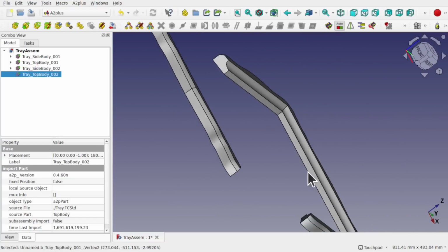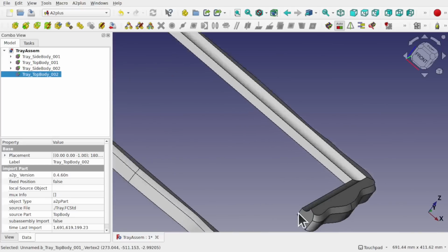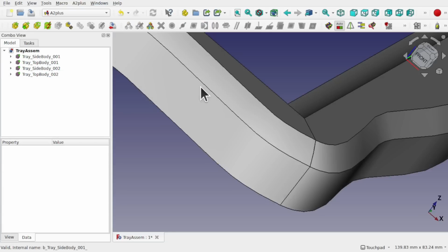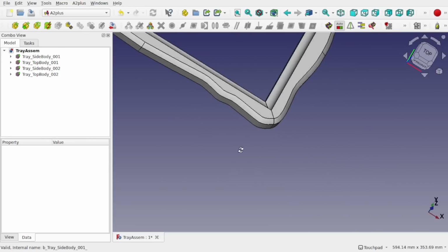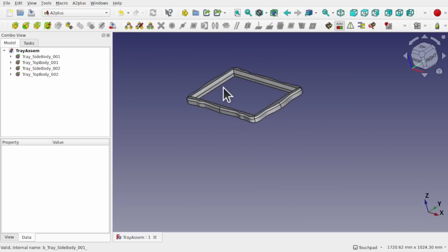Okay, so let's put mouse pointer over here so I can rotate this around, and make sure that we now hold down Control and select this point. Select that line, so click it again, still holding down Control, and select that point. So you can see both of them selected on the left hand side. Coincident on that, accept that, and we are assembled. Save off the assembly, and that's it.